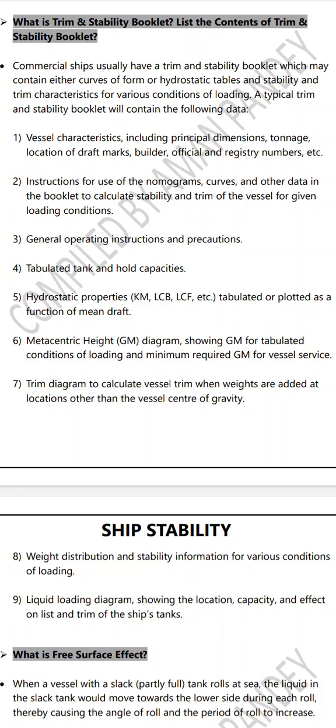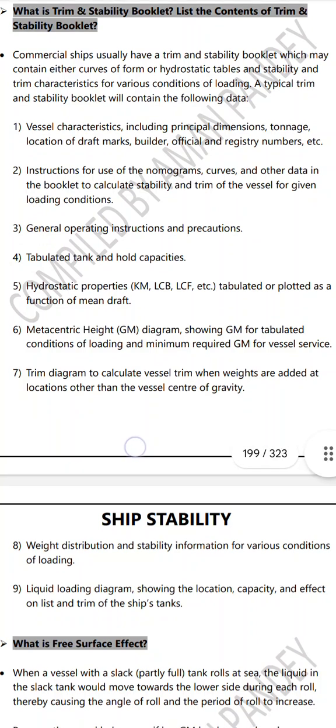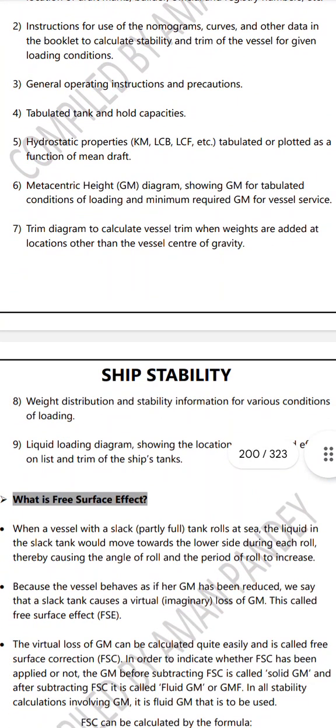Trim diagram to calculate vessel trim when weights are added at a location other than the vessel's center of gravity. Weight distribution stability information for various conditions of loading. Liquid loading diagram showing the location, capacity, and effect on list and trim of the ship's tanks.